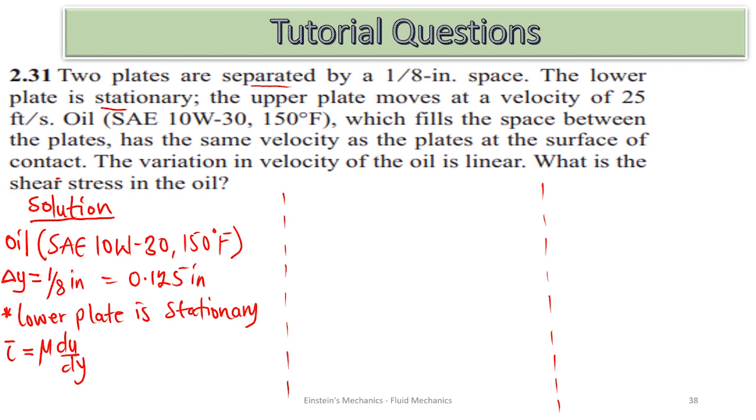Because the question says we are to find the shear stress in the oil. So what is the viscosity of the oil? This type of oil, what is its viscosity? And the viscosity of the oil can be obtained from tables. It is a constant value, SAE 10W30. Its viscosity is a constant value at 150 Fahrenheit.